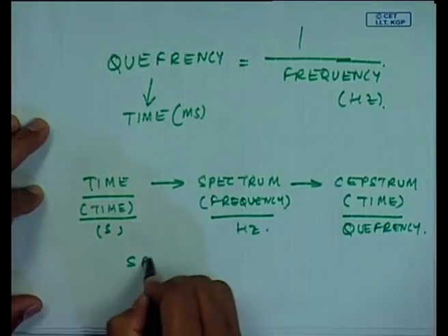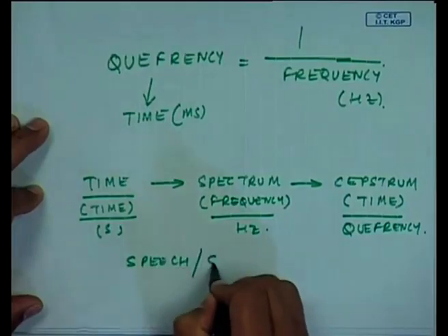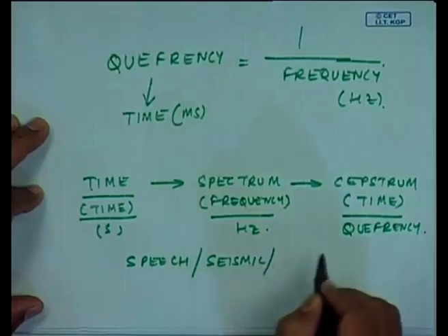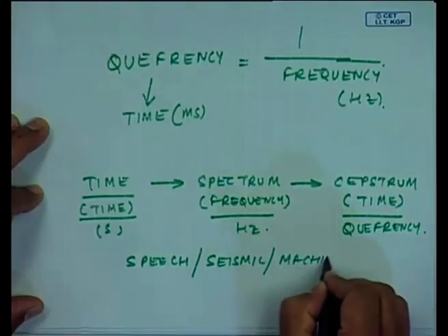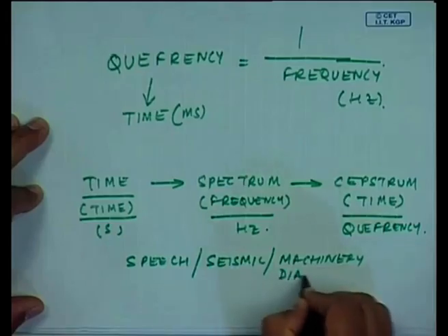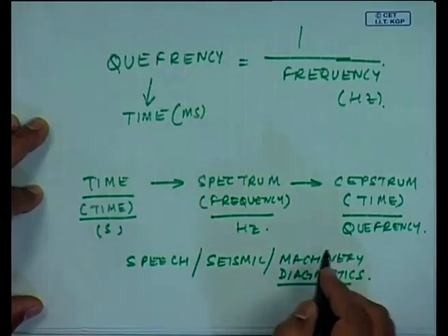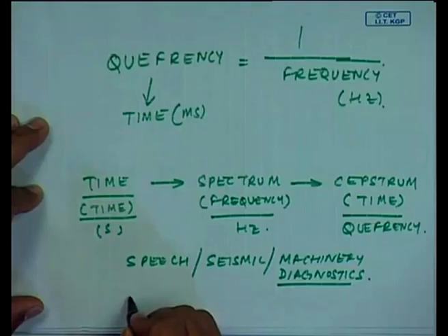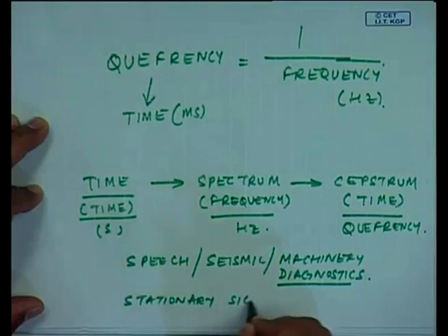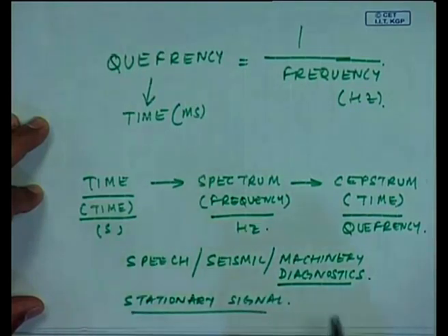So, Cepstrum applications are also in speech, seismic, and then of course, in machinery diagnostics. This is not a real time operation, this is on a stationary signal. I may not be able to do Cepstrum on a non stationary signal. For example, one transient, it will be very difficult. Okay. But if this transient is captured, we can do some sort of an analysis of it.